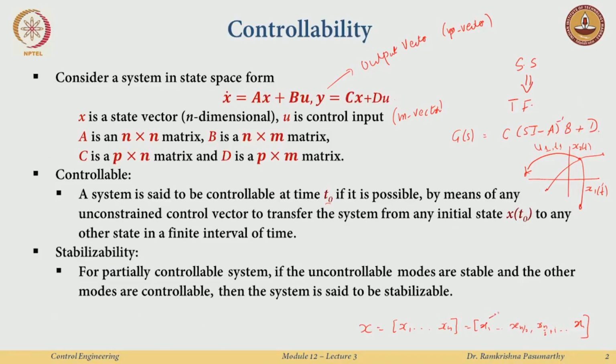Okay. So these are controllable states, these are uncontrollable states. Now, what can I do with these systems is I just ask a question: are these systems stabilizable? It is a little weaker notion of controllability. So, I can do anything good with the system as long as the uncontrollable modes are stable. Right? If these are stable, then I can do something with the controllable modes here.